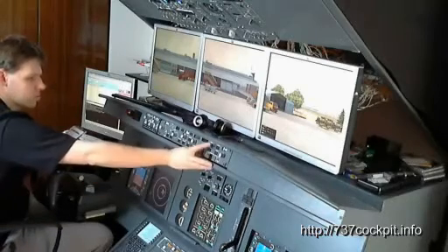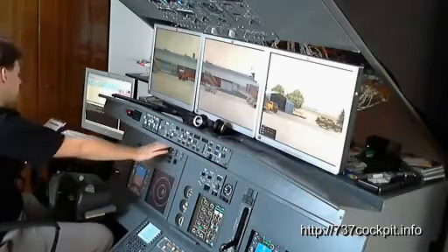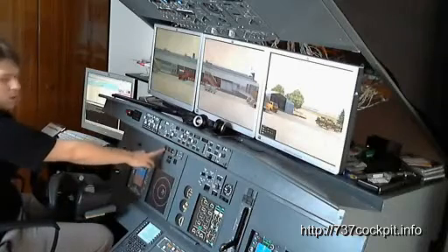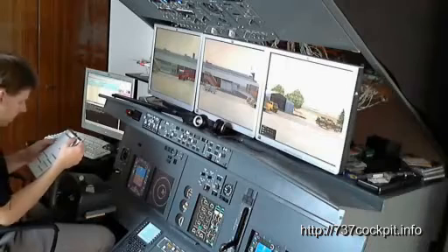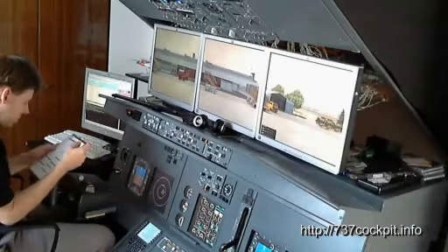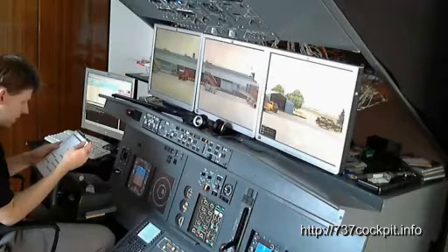Autopilot is disengaged, so we engage and disengage the autopilot, so we can check also in our main instrument panel. We have the indication autopilot, press to reset to remove the indication. Landing gear lever is down and checked, flaps up and no light, speedbrake and reflectors off.